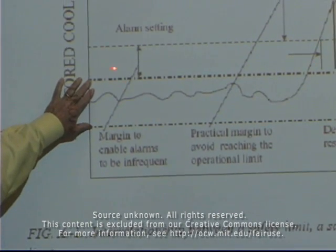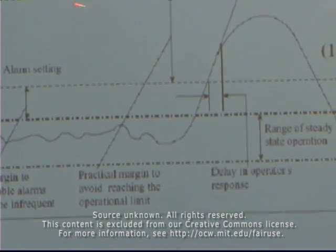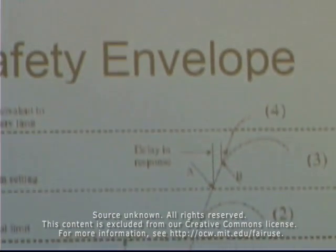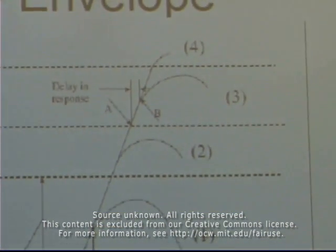So you have certain margins of operating, which would be in this band, and your alarm set points trigger you to keep within your operational limit, and you can restore to steady state operation. And then above that is where your ultimate safety protection systems will keep you from getting into bad trouble.